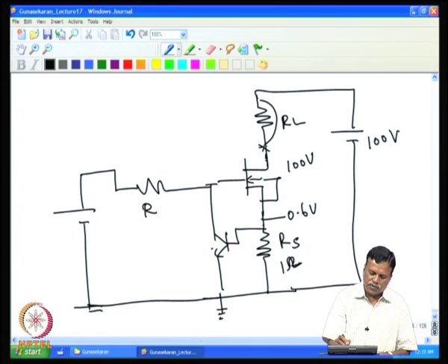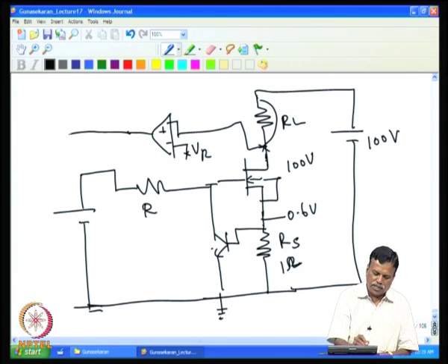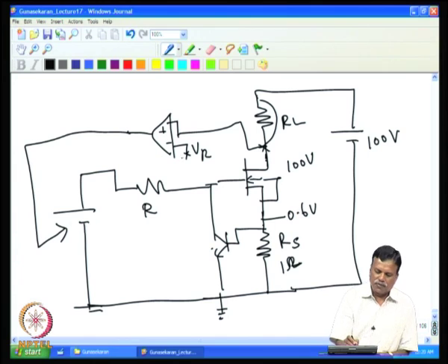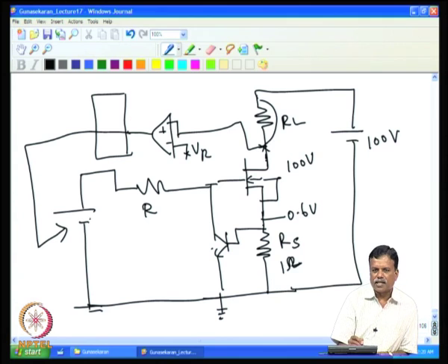So I can say that when the voltage at this point goes more than 2 volts, the MOSFET is taken to a higher level. So one can sense this voltage, and if it is higher than the prescribed amount, say 2 volts, which I can set as the reference, then the output goes high, and one can remove the source drive itself. Once the drive is removed, automatically no switching takes place and the MOSFET goes off. Of course, we have to have a latch such that once it goes high, it never comes back again. So that kind of arrangement can be done.